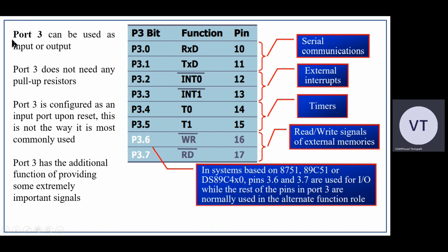Now coming to port 3, it can be used as input output ports. You don't need to connect any pull-up resistors. These will be available inside the microcontroller itself. Port 3 is configured as input output port at reset. This is not the way, but generally we don't use port 3 like any other port, as it's not meant for that.